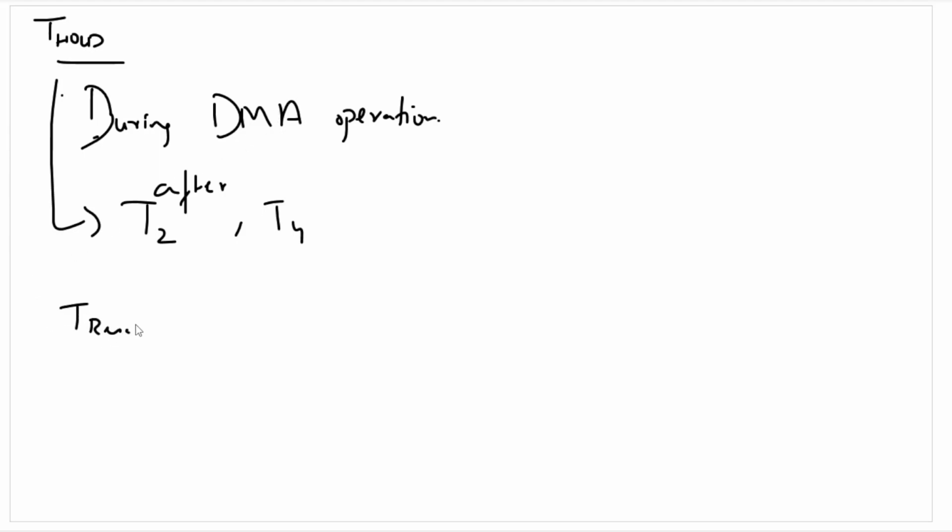So this state is the default. By default, the microprocessor will enter this state, and it will continue to remain in this state as long as reset in is not equal to 1. After reset in becomes equal to 1, the microprocessor enters the T1 state of the machine cycle.